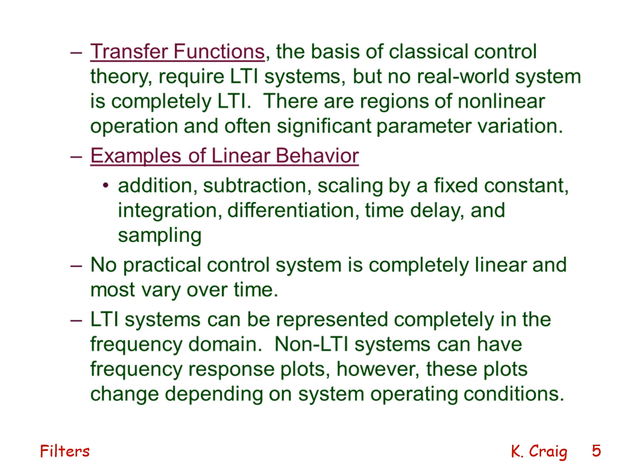Examples of linear behavior include addition, subtraction, scaling by a fixed constant, integration, differentiation, time delay, and sampling. No practical control system is completely linear, and most vary over time. Linear time invariant systems can be represented completely in the frequency domain. Non-linear time invariant systems can have frequency response plots. However, these plots change depending on system operating conditions.